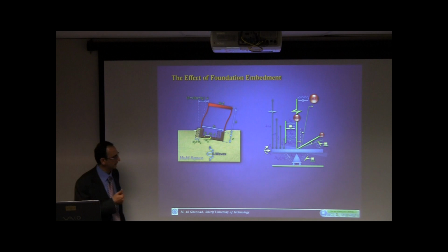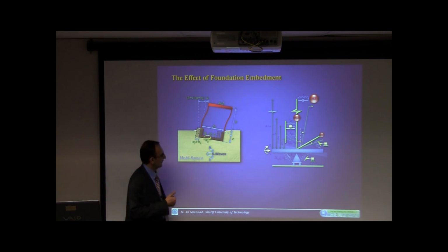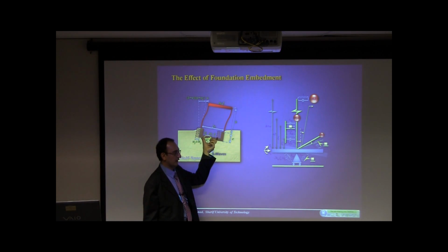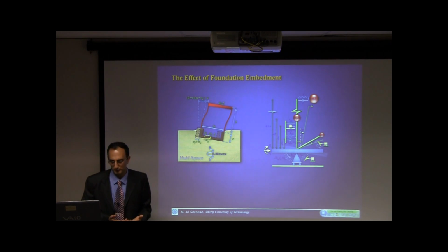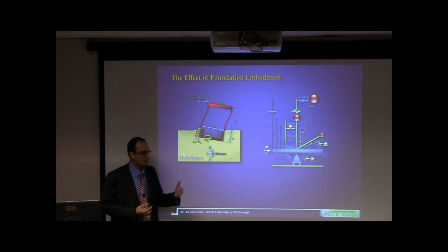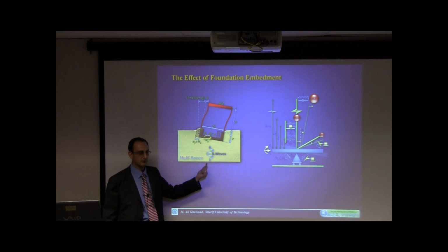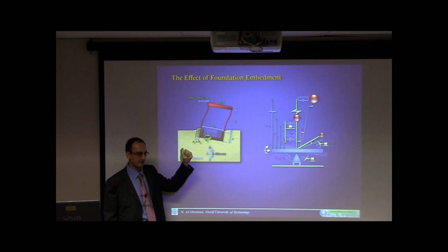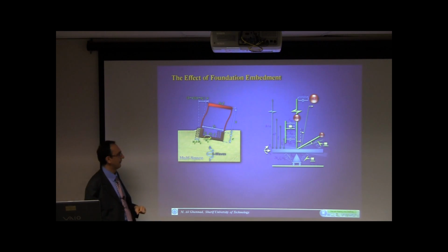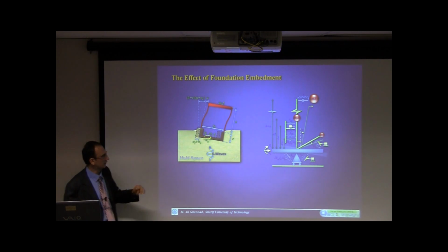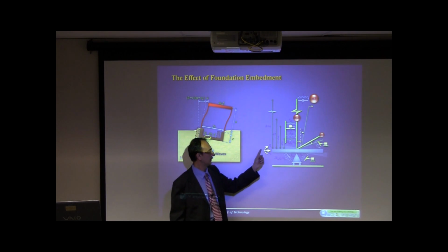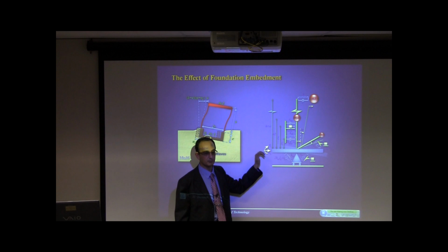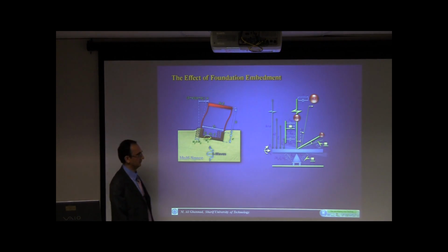And the point is that for the case of embedded foundations, you have to consider the kinematic interaction also. Even for the simple case of vertically propagating shear waves, as I talked about in the first slides, you have a kinematic interaction effect, and you have rocking input motion. So you have to consider that.